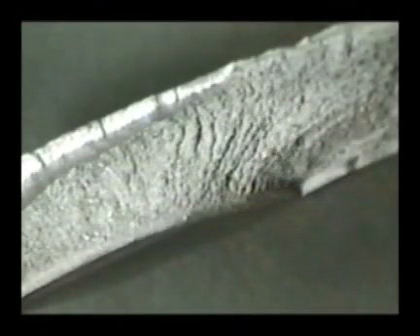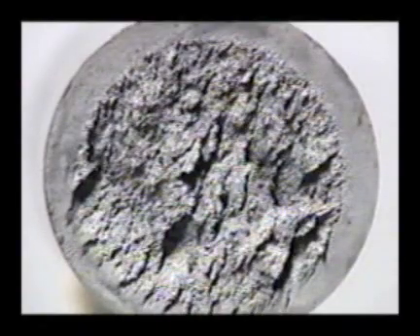This gear tooth fracture has a very rough texture, gray color, and chevrons, all characteristics of a cleavage fracture. This cylinder rod cleavage fracture exhibits a rough surface, gray color, and very distinct chevrons. After cleaning the surface and looking at it with magnification, we notice it even sparkles a little.